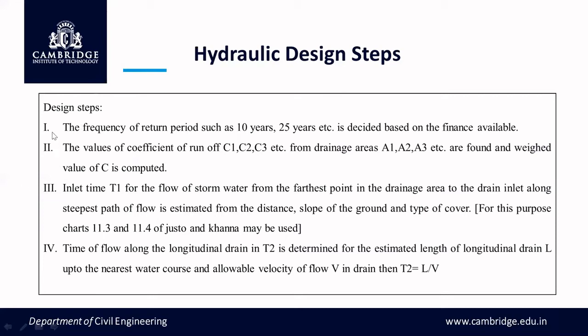The first one, the frequency of return periods such as 10 years, 25 years, etc. is decided based on the finance available. The values of coefficient of runoff C1, C2, C3, etc. for drainage areas A1, A2, A3, etc. are found and weighted value of C is computed.